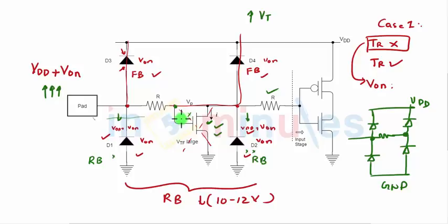And when this turns on, it will pass the current at its drain towards the source. So the current, or the charge, gets steered to ground. And again, this will tend to protect my circuit. So this is another way of protecting our circuit. So these are some of the ways. We can go ahead and study a few more ways where we can remove all the diodes, just keep this resistor and this transistor, and we can still achieve the functionality. This is all additional protection.